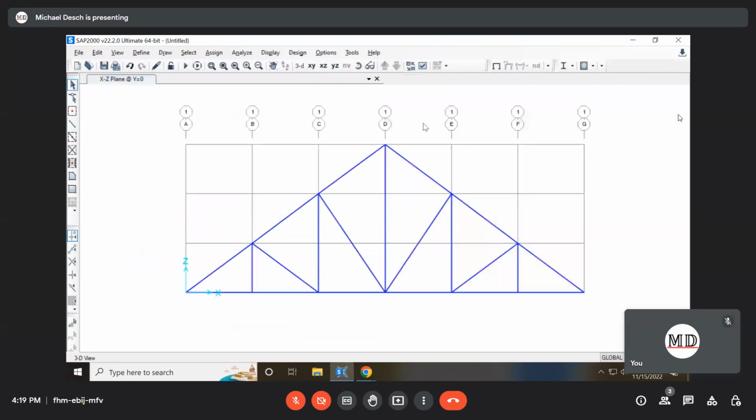So on the bottom, we should click on every division. Exactly, yeah. Because we have joints at every single one of these divisions between the webs, we want to make sure we have a joint at every single one of those and our members aren't continuous across them. Make sense? Okay, so our geometry should look like this.